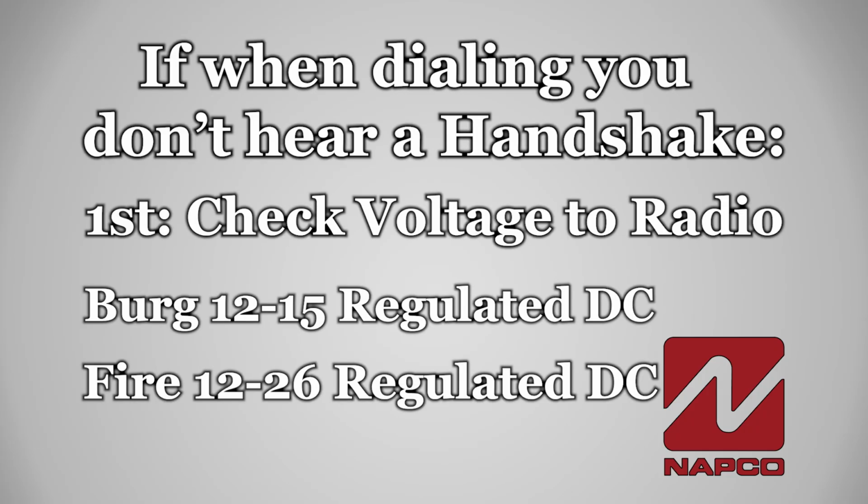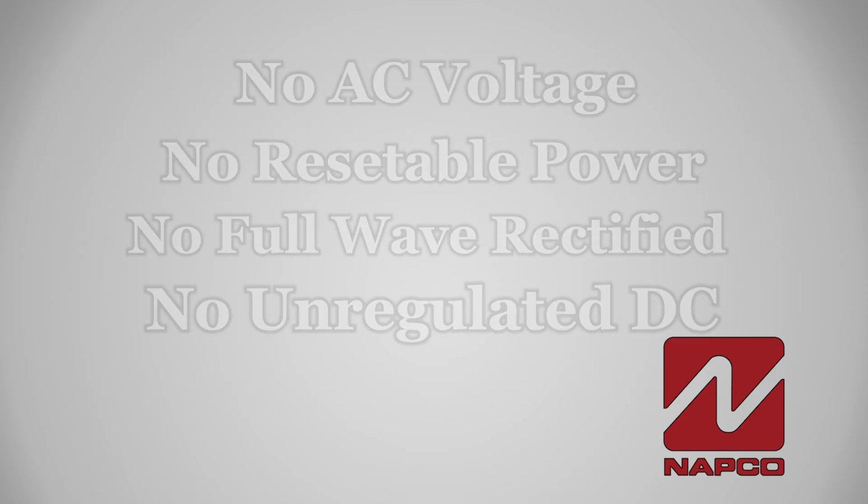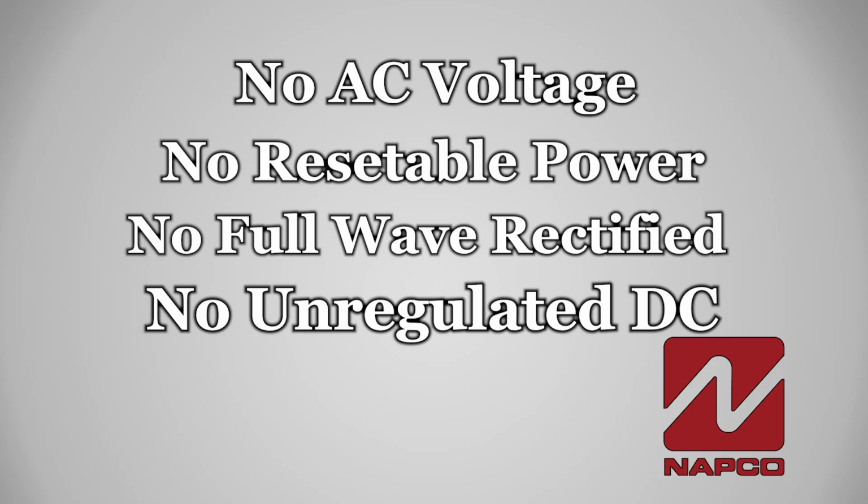If you dial to your radio, or when your panel dials to your radio, you don't hear a handshake, first, check your voltage to your radio. If it's a Berg radio, make sure it's getting between 12 and 15 VDC regulated power. If it's a fire radio, make sure it's getting between 12 and 26 VDC regulated power. No AC voltage, no resettable power, no full wave rectified, and no unregulated DC.